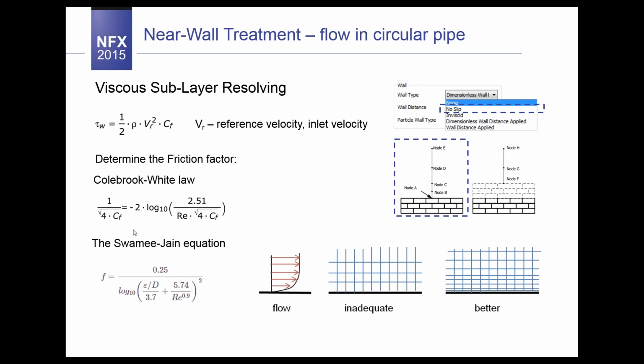This friction factor can be estimated from the Colebrook and White law, but if this is, let's say, too complex for some of you, you can use this equation, but again according to some condition on the value of the Reynolds number, because we have to open the book or use some reference material to study which formula is valid in which case. I'm not saying that this formula is valid for every case, but I'm using it as an example.